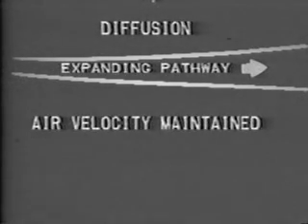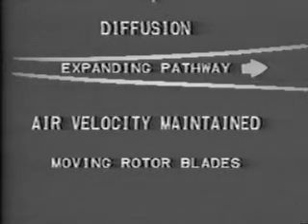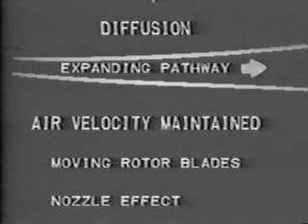Diffusion is the principle of increasing air pressure by forcing air through an expanding pathway. Air velocity is maintained by energy from moving rotor blades and the nozzle effect between rotors and stators.